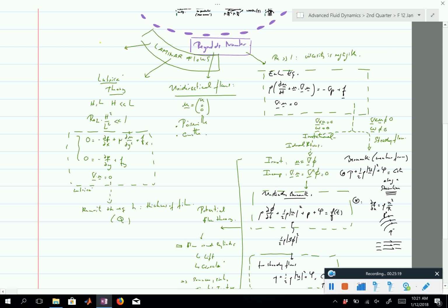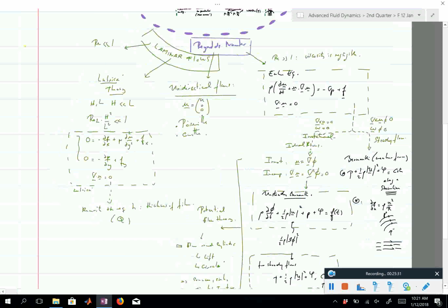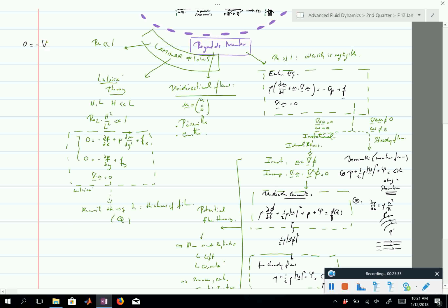That is just a case where the Reynolds number is really small, and the inertial term just drops out because you are in the Stokes regime. In that case, the equations are just everything without the inertial term, plus F, and those are the Stokes equations.